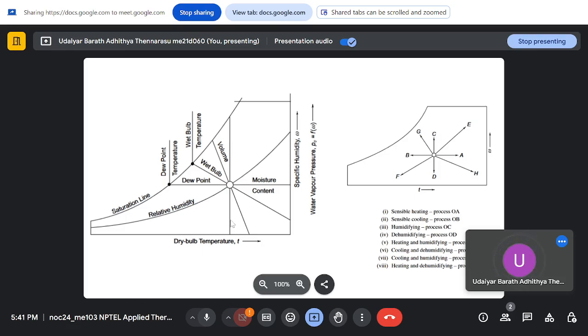So with that, next is your psychrometry. We saw psychrometric processes and how the psychrometric chart looks. So what are the quantities defined there? You have the moisture content, given as the specific humidity, and then you have relative humidity, how much you are varying from the saturation condition, and then you have this saturation line where the air is totally saturated,